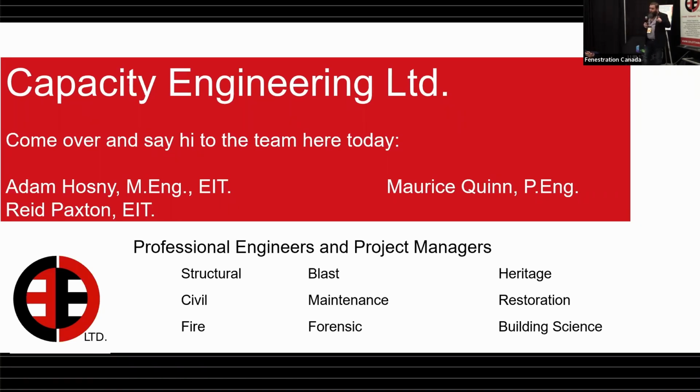So in Canada, remember, the code is the functional statements. You're going to give them a reasonable water tightness. That's all the code says. After that, there are acceptable solutions that reference a whole bunch of standards. So unless somebody did some pie in the sky fancy thing, it's the acceptable standards that are going to be applied. Okay, acceptable solution, which includes reference standards. The reference standard is A440. A440 in Canada has the supplementary standard.